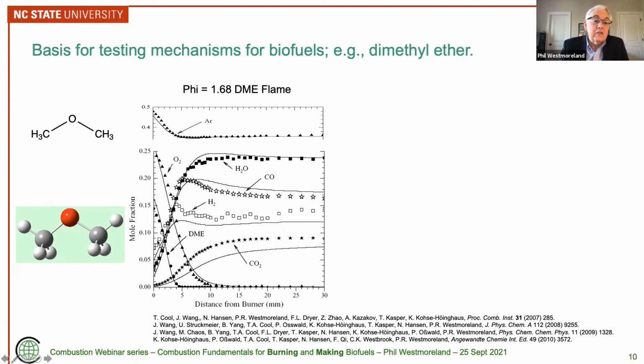And you can see that just looking at the hydrogen, the CO2, the carbon. It's actually non-zero at the surface, which is physically realistic. The so-called Danckwerts boundary conditions were taken into account to recognize that when you've got a region where things can diffuse, like the open flame, compared to a region like the inside of a burner where they can't, then you're going to have the convective flux in equals convective flux minus the diffusive flux coming back to it.